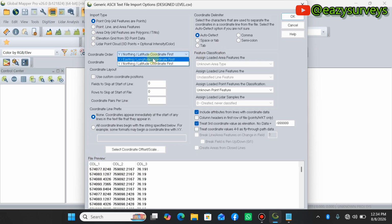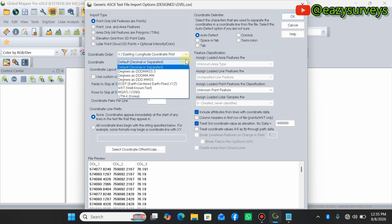So you need to select the first format on the column. In my case, distance, then northing. After that, this is auto detected. Leave it on default. There's nothing much to do again. Then you just click on OK.